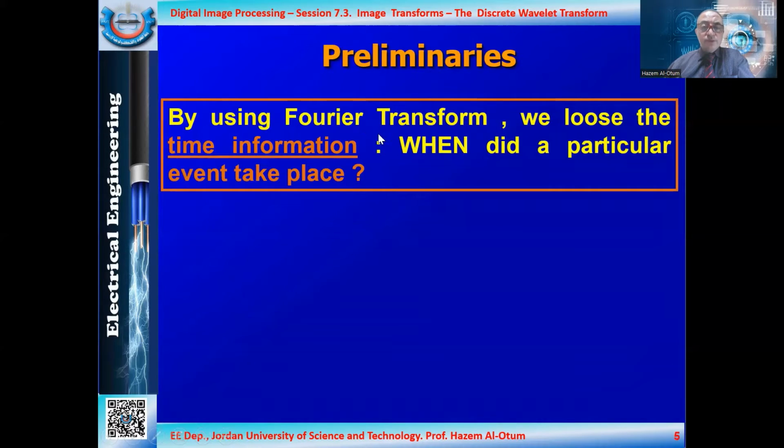When you apply the summation or the integration, you are averaging over a long time observation in the time domain to get the frequency content. This will cause you to lose the particular event in time, and how it has been reflected in frequency.